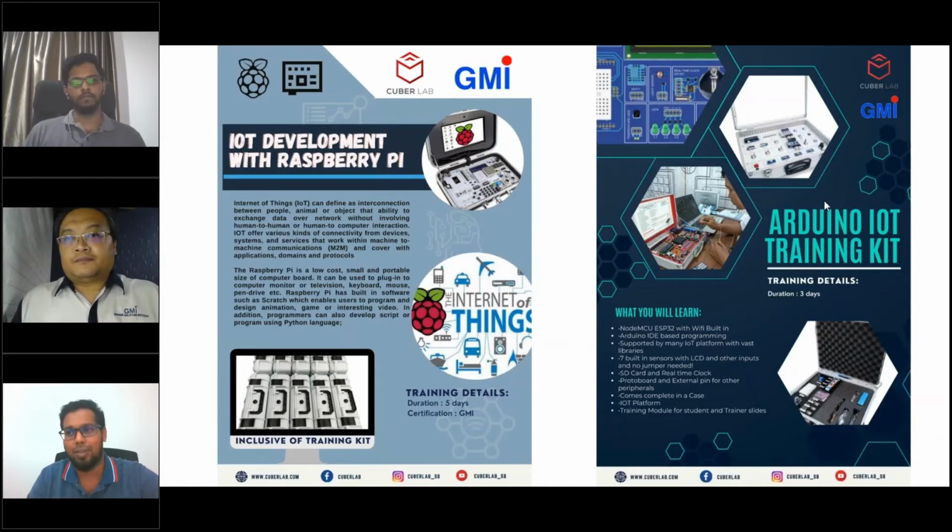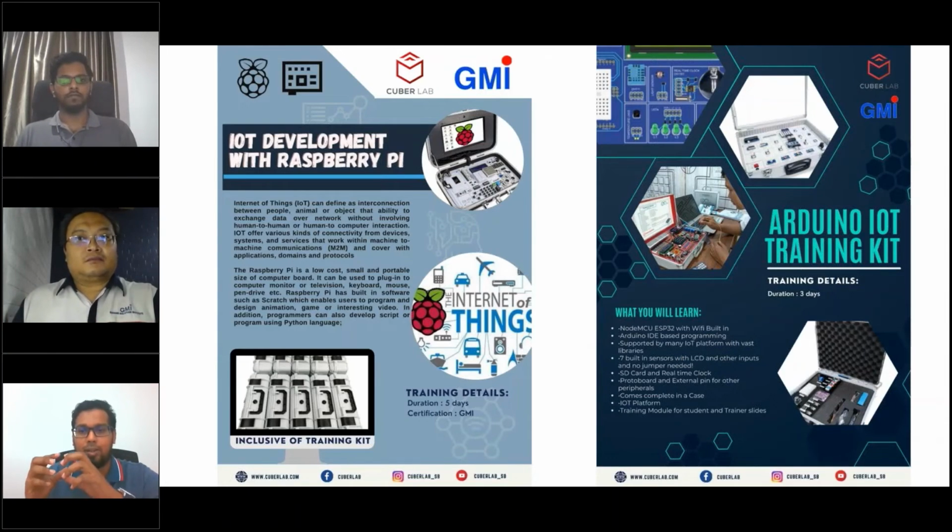And also in some cases that we have seen, some companies have really mixed production, where maybe they run one part only for 6 months, and then the next quarter they will change the part. For this type of company, the 6-axis robot is better because you can just reprogram it to do different tasks easily, rather than being fixed with a linear robot, which has limitations, while a 6-axis robot can do much more. After 6 months or 3 months of assembling this product, when a new product comes in, you can just reprogram the robot, change the end effector and use it. So it all depends on your application.